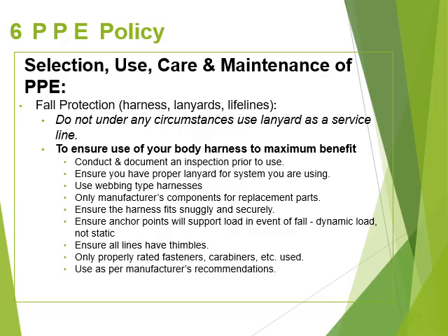This is the load in motion, or dynamic load, which differs greatly from a static load, body weight, and clothing. Ensure all lines have thimbles. Ensure only properly rated fasteners and so on are used with all fall protection systems. The system is only as strong as its weakest component. Use the system only as designed for the pre-approved engineered operations and tasks, as per manufacturer's recommendations.